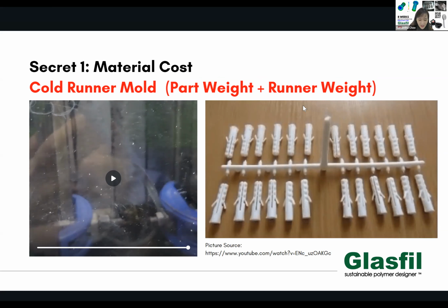Let me see whether anyone answered it correctly. Did anyone get 24 cavities? Okay, so this particular mold has 24. So are we going to calculate this runner weight and this part weight? They will ask you what is the weight of the plastic. The weight of the plastic is actually inclusive of the part weight together with the runner weight.